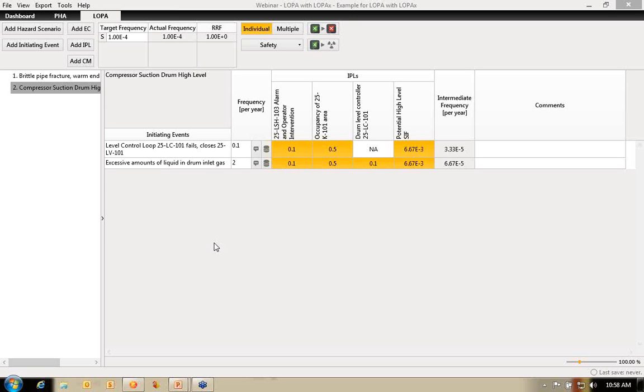We came to the conclusion that we needed quite a lot of risk reduction because it's a high severity event. At the same time, that lunchroom was only occupied maybe 1 hour out of 24, or maybe 2 hours out of 24. So there's a 22 out of 24 probability that when that event occurs, there's nobody in that area. So that's a scenario where you can account for occupancy.